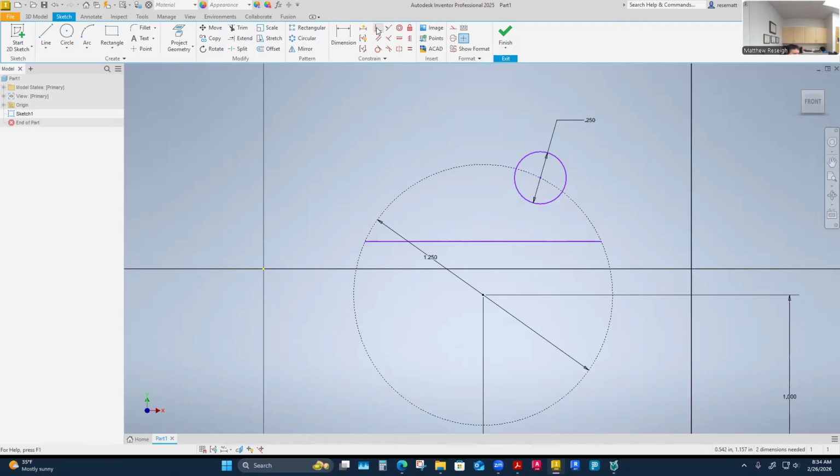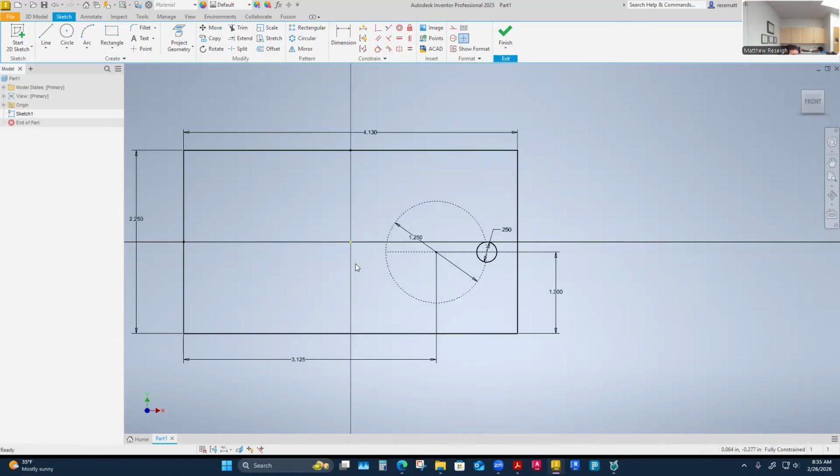I'm gonna do a coincident constraint to this line center point to this center point here. That's all it takes to constrain that. It's bound in here. It's a horizontal line. So this is also just for me as a construction line that I'm using to place this. I'm going to coincident constrain to the center to that line end right there. And that's kind of the location for at least one of mine.